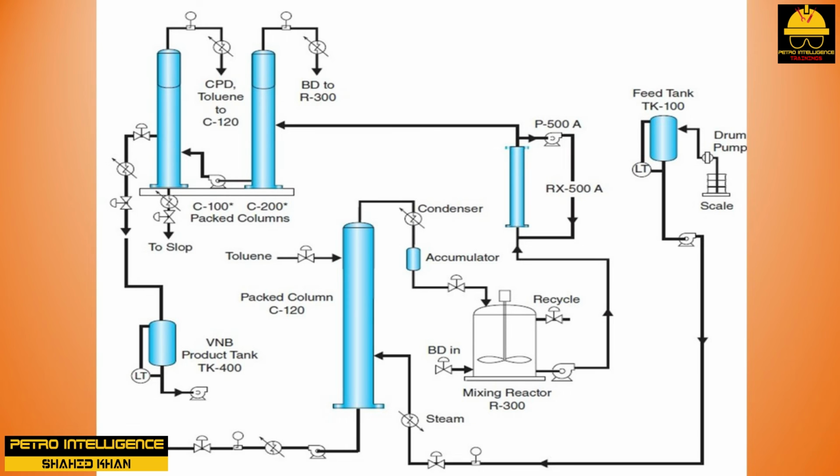The outer jacket is filled with hot oil that maintains a specific set point. A large centrifugal pump circulates the feed through the reactor as the synthesis reaction occurs. The reactor is mounted vertically, and flow moves clockwise through the tubes. Special inhibitors are added to the feed to limit the formation of insoluble polymer during operation.